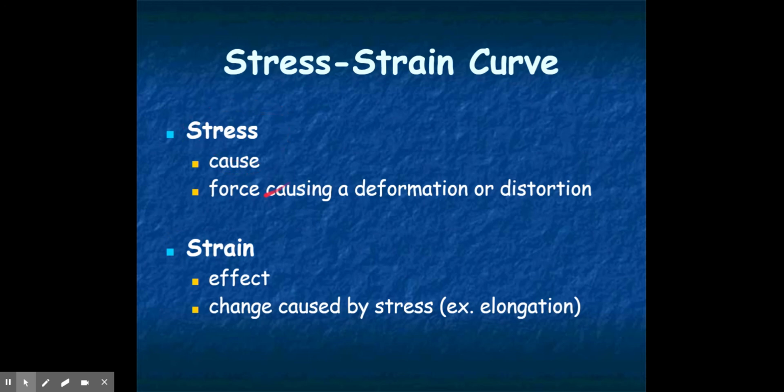And remember, stress isn't just a force; it's the applied force to an area. A lot of terms bouncing back and forth, and they sort of mean the same thing, but there is a difference. So stress is a kind of force, but it's not force. Stress is that force applied to an object, and strain is the change or the deformation that's caused by the stress.